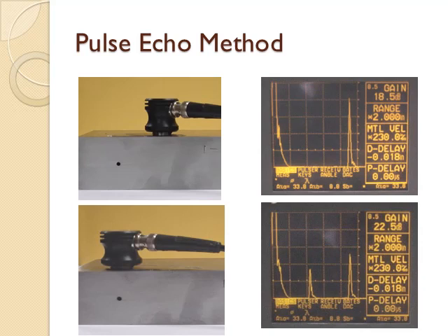If the heights of pulse A and pulse B are almost the same, and in between the two pulses we do not find any pulses, the material is in good condition. While checking, if we have some more pulse in between pulse A and pulse B, we come to know the material has some flaw in it.